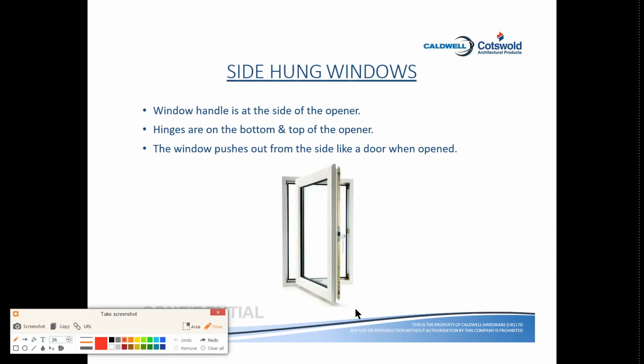In this case, this butt hinges type of window is required, which could be opened from the pivot point till end, or a 90-degree opening is required. The more the opening you achieve, the more easily a person can run out of the window, or a firefighting person can easily enter from outside to inside.